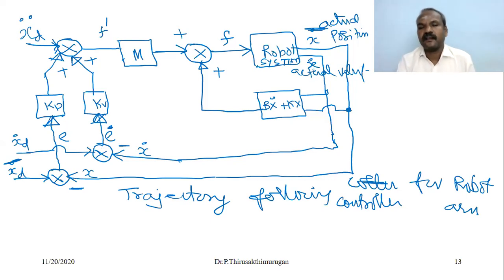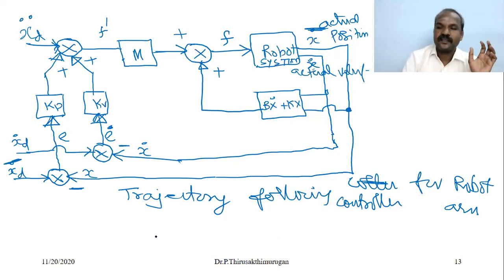Since this is a second order differential equation for which we can choose the coefficients, we can design any response we wish. Often critical damping is our choice. Such an equation is sometimes called error space. This controller choice is written as error space, since it describes the evolution of error related to the desired trajectory. This figure shows the block diagram of the trajectory following controller.